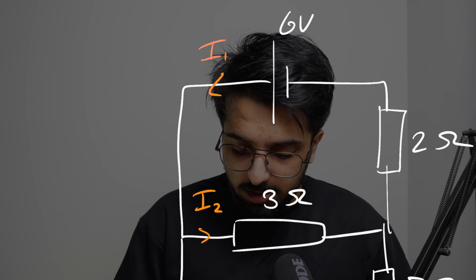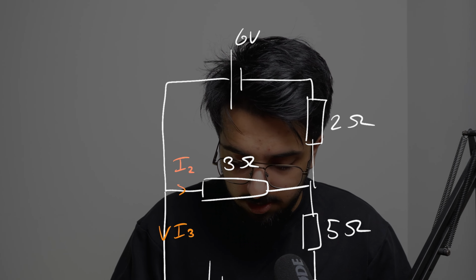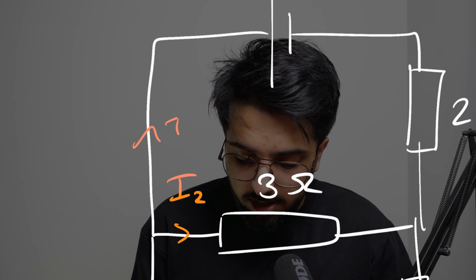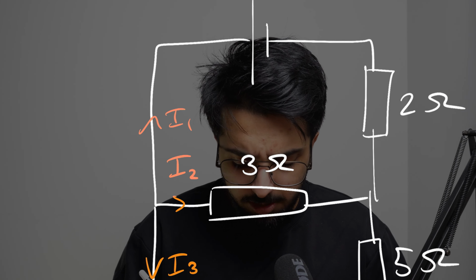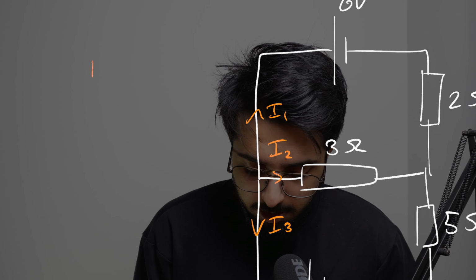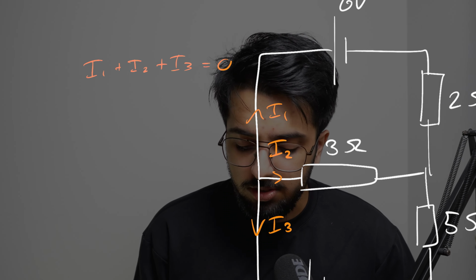So this method, we still use our Kirchhoff current law, okay? So let's redefine this and say this is I1 right here, okay? Notice that's just the exact same thing, but we're just flipping the sign, okay? And so therefore, I1 plus I2 plus I3 is all equal to 0, okay?